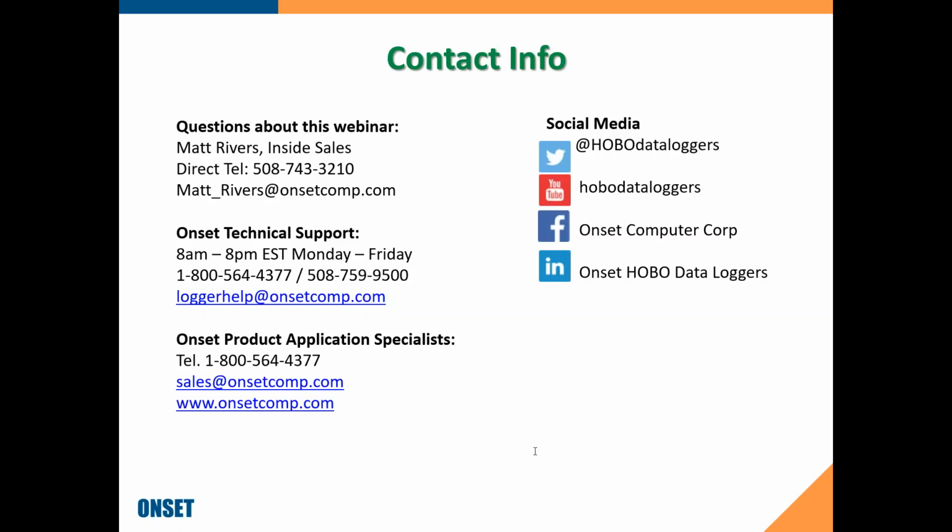So state on-off is exactly what it is. It's going to record a point of data when a change occurs. Specifically when we're talking about lighting or motors or a dry set of contacts opening and closing, that is going to record when something happens. So with that contact closure as our example, when it closes, it says, okay, that contact closure closed, so it's active. It could be on, we'll say. When that contact closure opens again, it can say, okay, it's open, so we're going to say that's off.